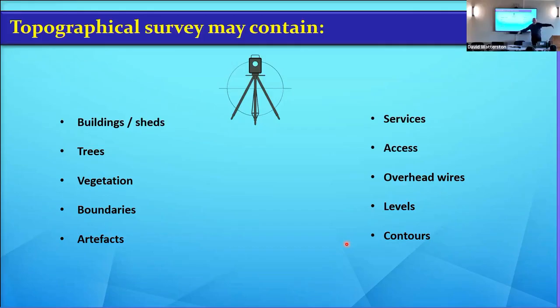But if it's only a metre or two, you could get them just to do the building outline, the back of path, what the boundary is, whether it's a wall or a hedge, the face of the kerb line, and probably go 10 metres either side, drop kerbs and everything. Are there any yellow lines on it? Because if you're bringing a truck by, and it's a very busy road, you want to know what the restrictions are. So look at lamp poles and see what the parking restrictions are, as well as looking for overhead wires and cables and trees and all the rest of it.